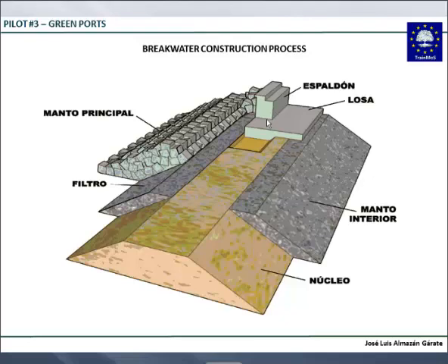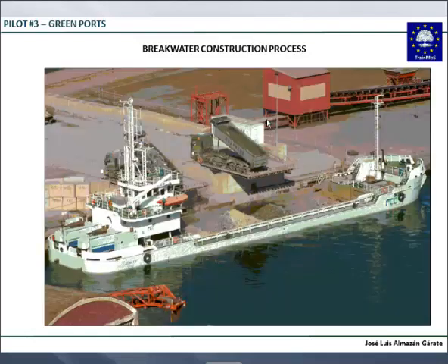So when you have bigger means to construct dikes, you can go faster, and naturally you should build during the summer where there's no energy, and during the winter you just protect your work and wait for the summer, because normally you cannot work in winter because you will lose too much material.